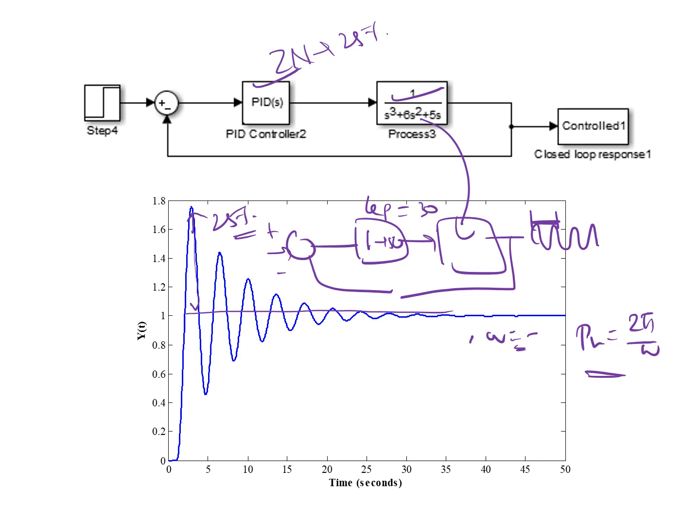So MATLAB is so easy. You just have to connect the controller, just one gain value, connect the process, and keep on changing the value till you get sustained oscillations. Once it is done, note down this value and note down the successive peaks. Find the value and substitute in the equation and you will get the controller parameters. Then implement the controller parameters.